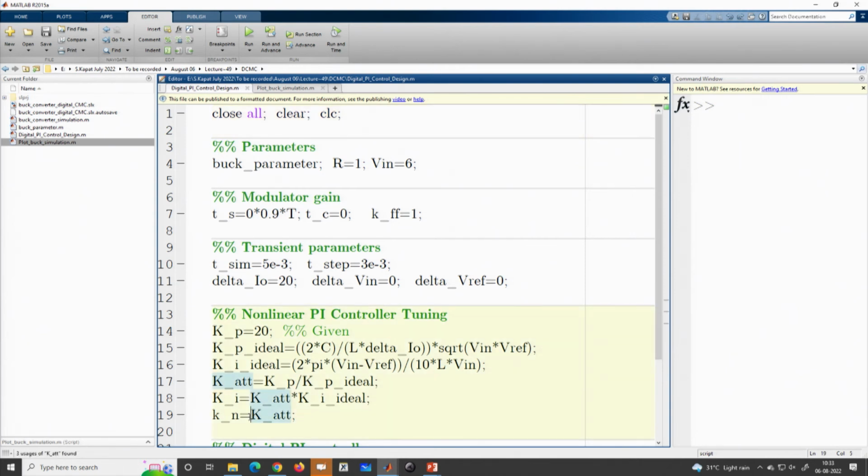One way, because you cannot do anything about the delay, but there is an additional overshoot. So, you need to increase the current loop gain, so that it will create some kind of damping, because the inductor current minus load current resembles the capacitor current, which gives some information of the derivative of the output voltage. If you can increase this term, then the derivative action will come and it will add some phase boost. As a result, you can reduce some undershoot effect.